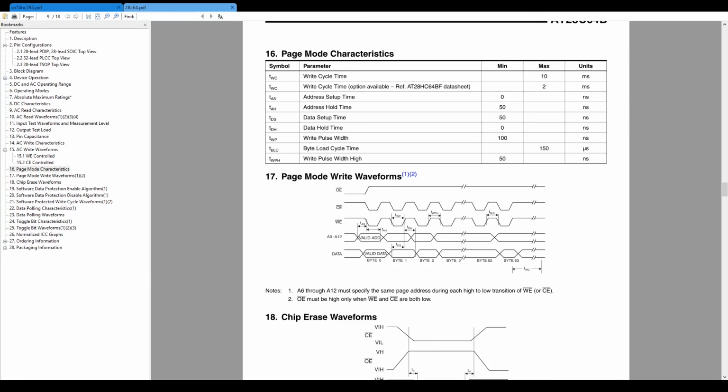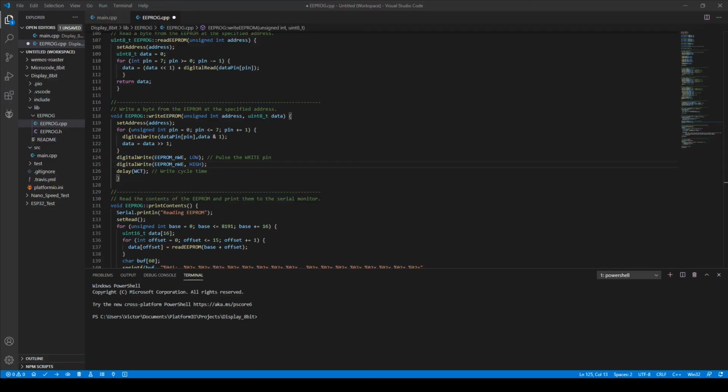And I just want to keep the code simple for now. It's already fast enough. You'll see when we program the EEPROM. It's already working fine. So we'll just wait the 10 milliseconds. And that's also why I have added this delay on each of the setup functions, the set standby, set write, and set read. So we would avoid entering the page writing mode at the beginning of a writing.